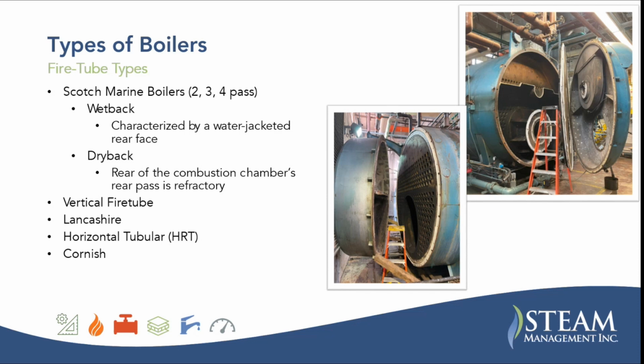And so you lose some efficiency there, but when you open the boiler, you can access all the tubes, so the accessibility is a little bit easier. On the dryback boilers, the back door is generally going to be heavier because it's full of refractory, a little bit harder to remove, where the wetback boilers, it's usually more like a plate or a set of plates that could be removed by hand. So there's just some differences there. Those are the two types.